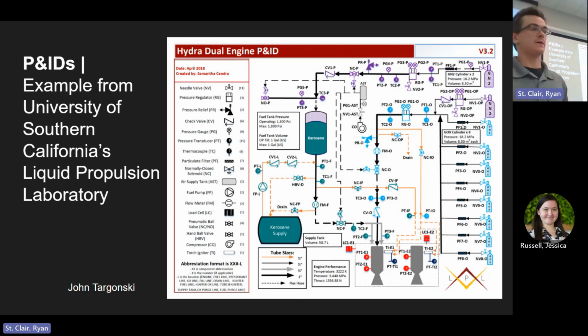It's because, again, they're concerned about that high pressure oxygen environment. They really want to make sure that there's no particulates along in there. Another interesting thing is, oh, you've got gaseous nitrogen in here. So why would you have that going into your engine? Well, it's very likely that they want to purge their system of all atmospheric air.